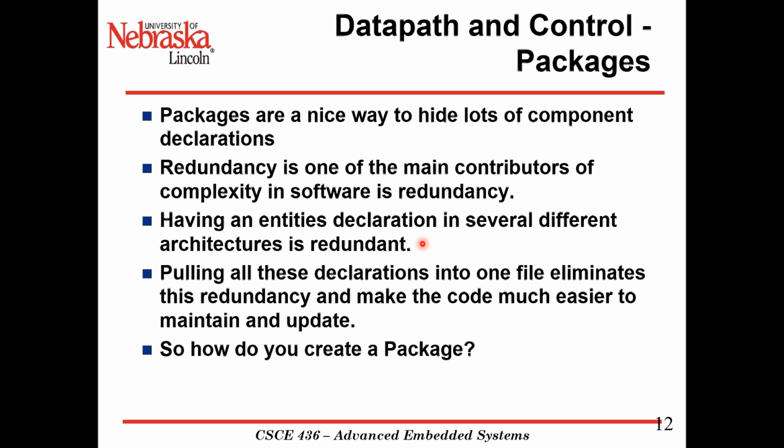So we just add that package to our project, and I'll give you an example in Lab 2, and all the component declarations are in one file, and so if we're using them multiple times, we don't have to update all declarations if we add one line to an instantiation.